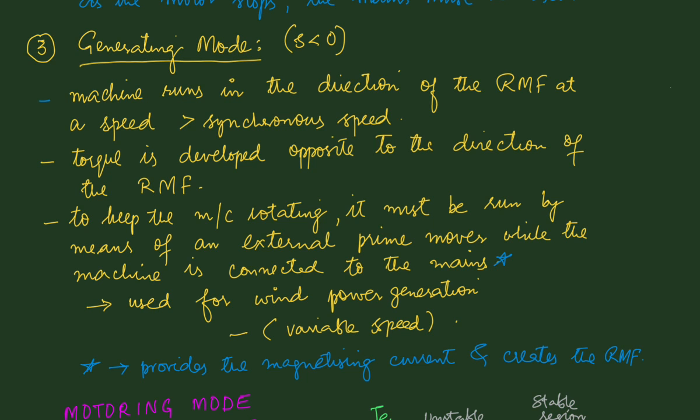An induction generator will keep supplying power satisfactorily to the grid at the frequency of the grid, even if the rotor speed is changing. But a synchronous generator used with variable frequencies cannot operate satisfactorily, because it will generate voltage with a variable frequency at variable rotor speeds.